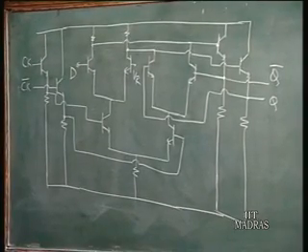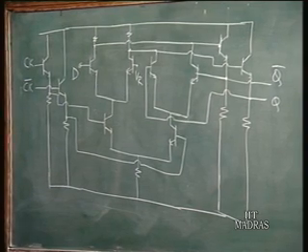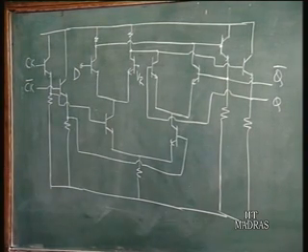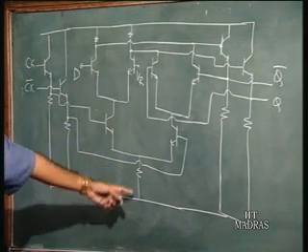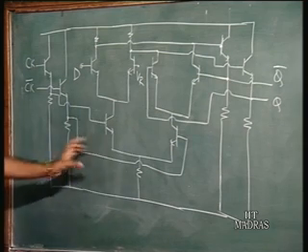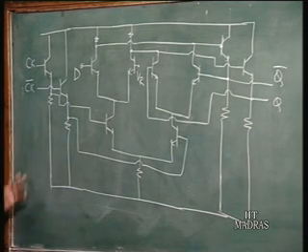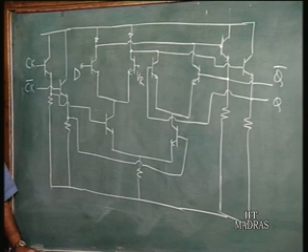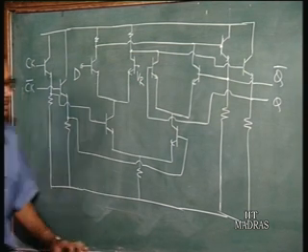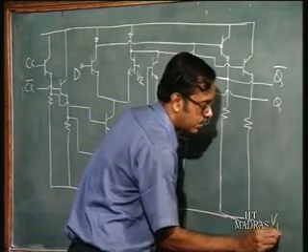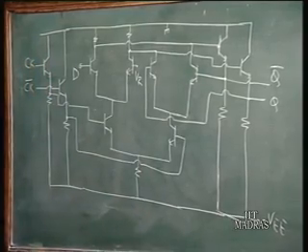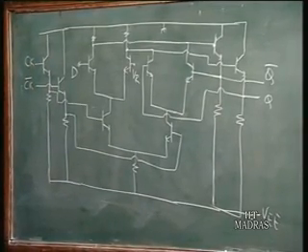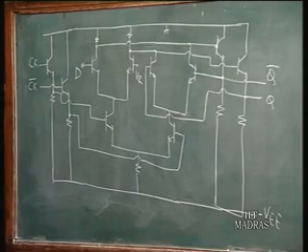Basically, as you can see, the power consumption is going to be almost the same as that of a simple OR NOR gate, okay, because you have one basic gate structure, the same power, except of course you have some emitter followers, level shifting circuits which also will draw some current, but they are quite small currents, okay. So, this is the power supply, okay. So, what you have here is, now you know what is a D flip flop.